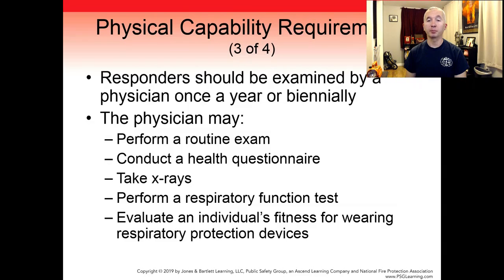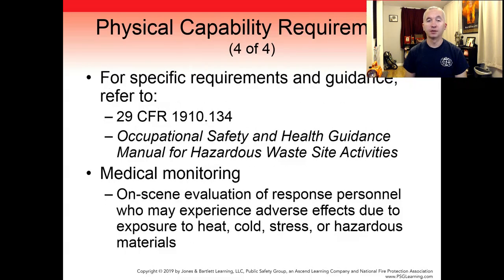The physician may perform a routine exam based on the expected tasks the employee could perform, conduct a health questionnaire, take x-rays and perform respiratory function tests, and evaluate the individual's fitness for wearing SCBAs and other respiratory protective devices. Specific requirements and guidance may be found in 29 CFR 1910.134 and the OSHA, EPA, NIOSH, USCG document, OSHA Safety and Health Guidance Manual for Hazardous Waste Site Activities.